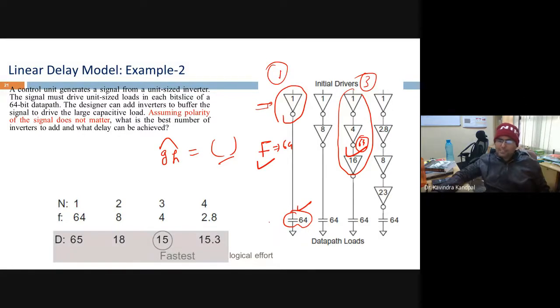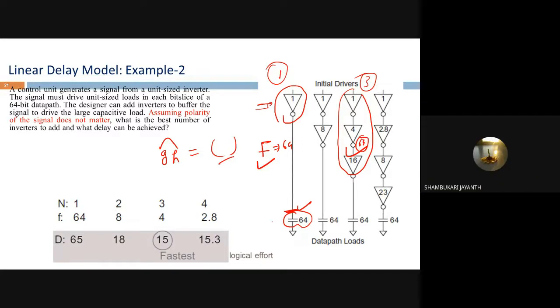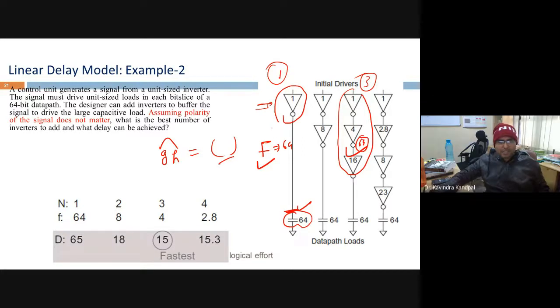But as already pointed out by one student on that particular day, if you increase the width, it also increases the input capacitance. So it is not that if you simply increase the W by L, it will keep helping. For a certain range you may get some improvement in delay, but finally it becomes constant, right?